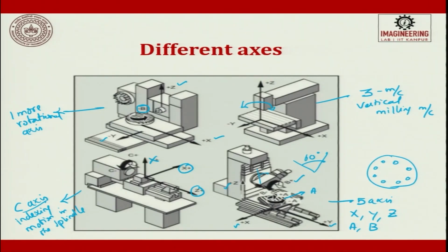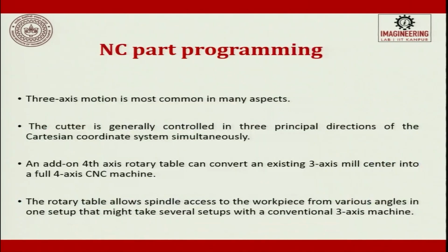So, you should understand first how to fix the axis using the right hand rule. It is very clearly said the spindle axis, powered spindle axis will be Z, then by the right hand rule you will have X and Y. So, now rotation about X becomes A, rotation about Y becomes B. Okay, and rotation about Z becomes C. So, here it is A and B, but this is a convention. Please look into the controller manual before writing a program.